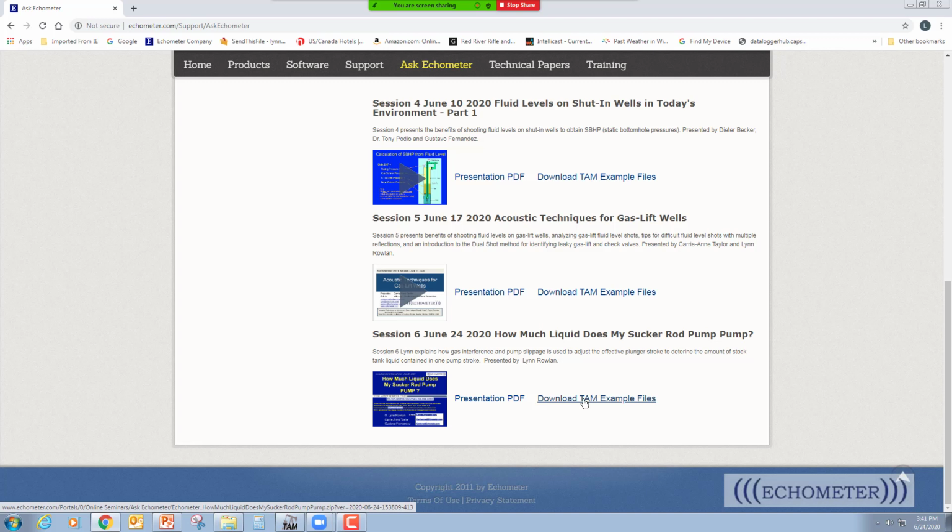So Gustavo, do we have any more questions to cover? We have one last comment from Tariq. Say I've got a perfect textbook pump card, an anchored tubing. The fluid level is at 2,800 feet. The pump is at 3,200. Shooting nipple 4,000. I'm not sure about it, but no fluid coming out of the bleed valve to take a buildup. Is there a possibility for a tubing leak or something else?